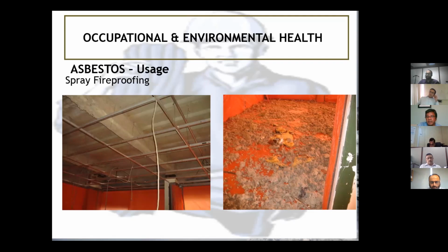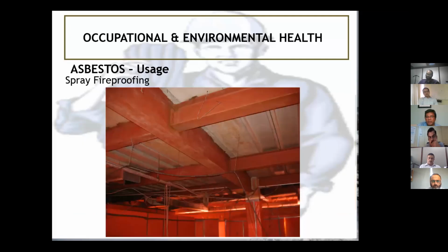On the left side, the picture is a fireproofing, which is asbestos containing. Right side is wool-like, turning to powder form with your hand pressure. This is when completely removed from the beams and columns. And once everything is clear, these beams are resprayed with non-asbestos materials.